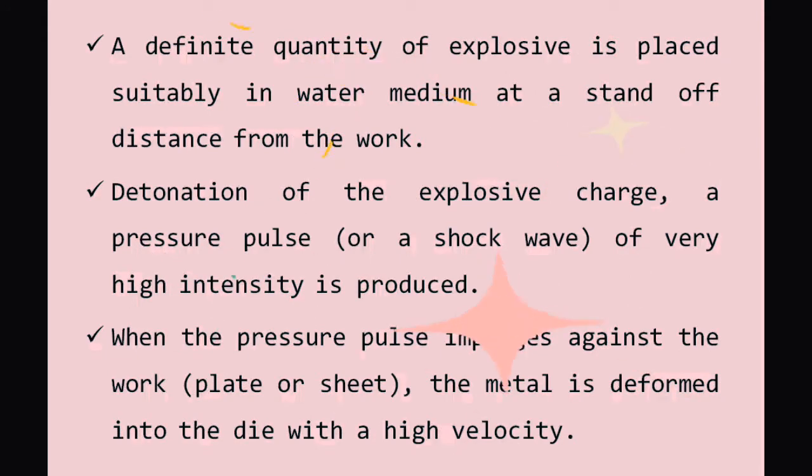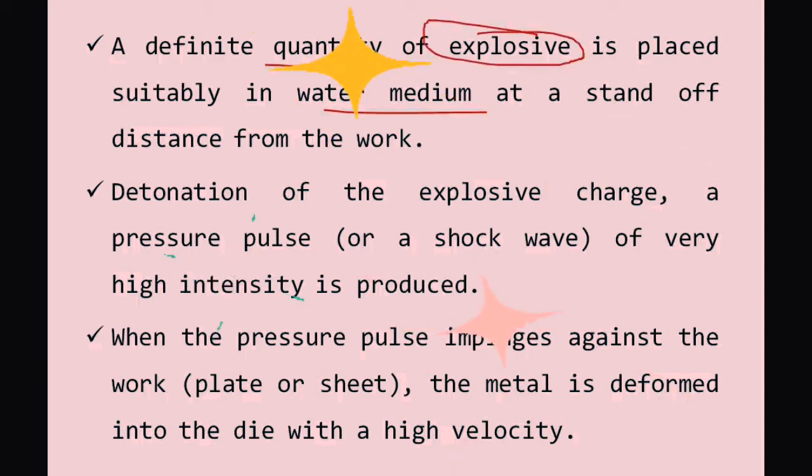A definite quantity of explosives is placed suitably in a water medium. How much quantity of explosives is needed has to be calculated first. Based on the material grade and the thickness of the material, you have to choose how much quantity of explosives is needed, at a stand-off distance from the work. Stand-off distance means how much distance there is from the object to the explosive location. This is the stand-off distance.